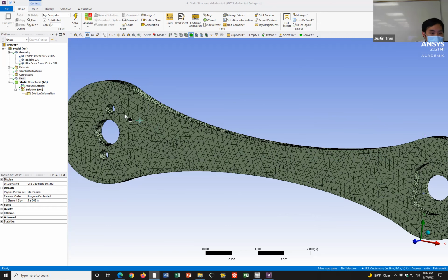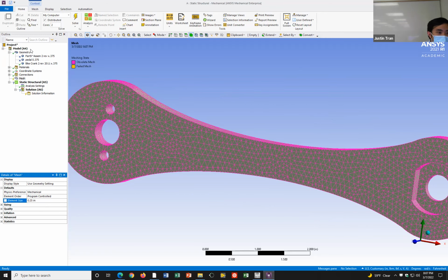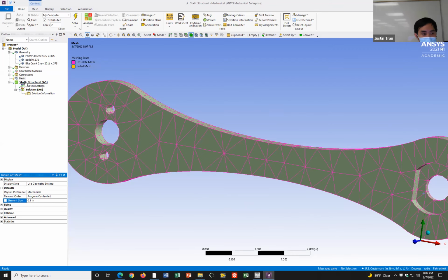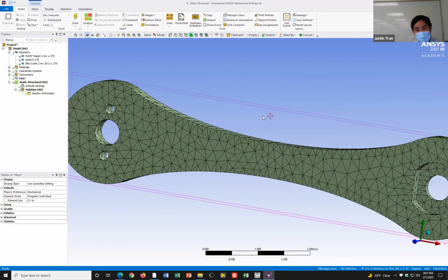And so you can see that, if we were to load a digital image on top of this mesh, it would be a lot higher quality than, say, if we did one on this mesh, right? And so if I change this to 0.25, this is going to be a much more coarse, much more janky image than before, right? But for this activity, I would say at least have a mesh sizing of 0.1, and then you should be okay. Okay. Any questions on this mesh? Okay. Oh, one more thing.